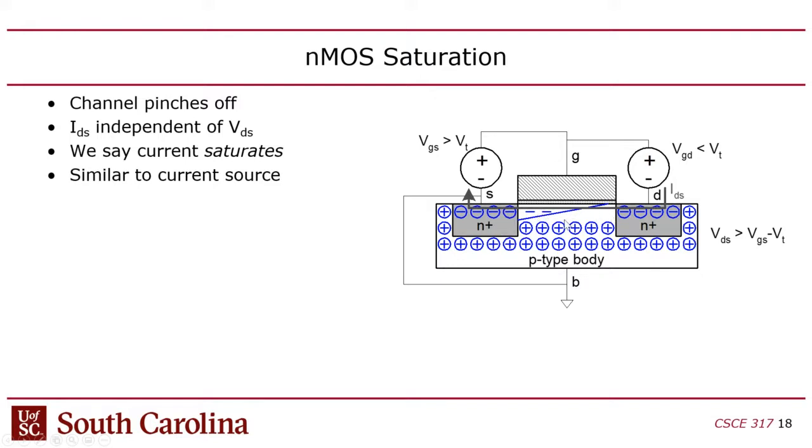But the width is the dimension you don't see. It's like the third dimension, like if you push back through the monitor there. That's the width, right? And the more width you have, the more current will flow when the transistor is in saturation mode, which means that the transistor will be able to switch a higher load faster.